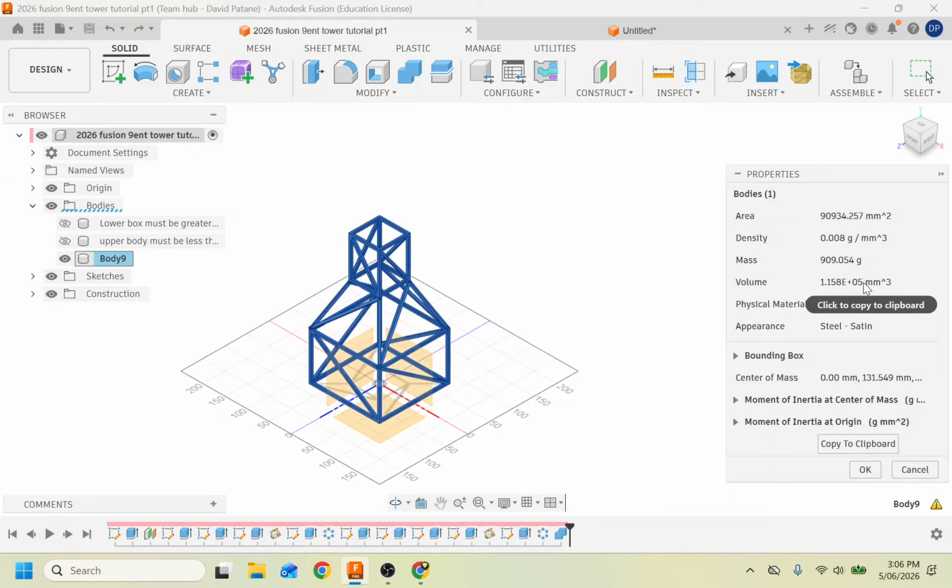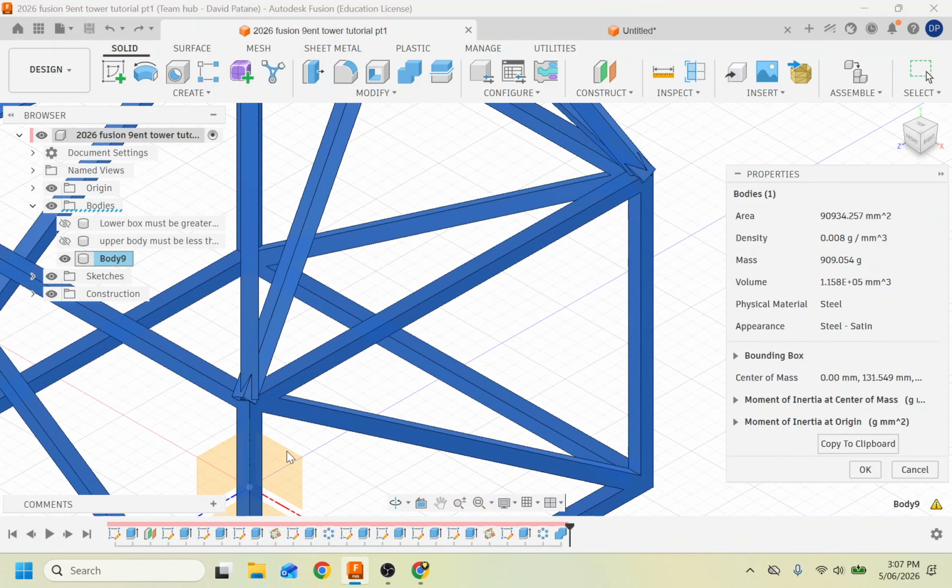They're like 905 millimeters, or the design requirement specifically said 900 millimeters, and you know its cross-section is 5 by 5 millimeters, and you have 8 rods, so you can find out the volume of balsa wood you have. So in your assessment task, when you have to prove that your design could be made out of balsa wood, you calculate the volume of balsa wood you have available and you compare it to this design over here.